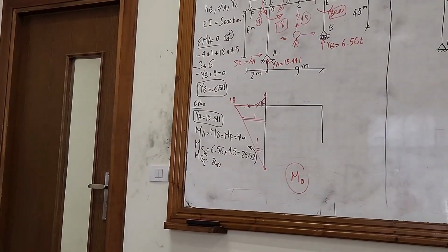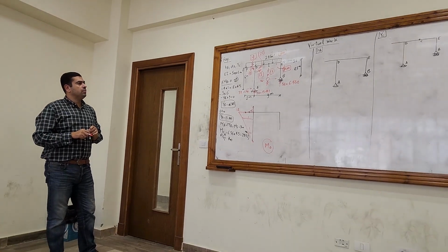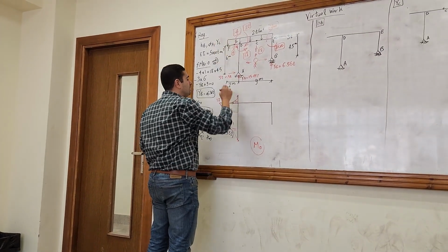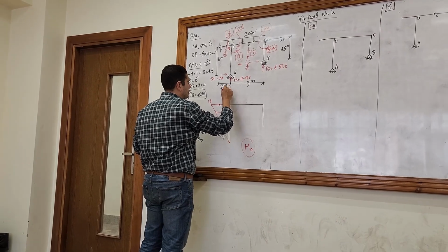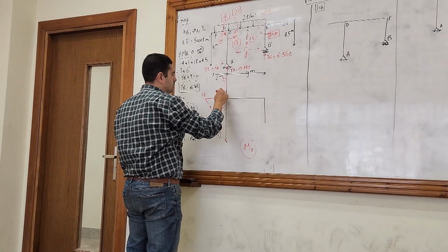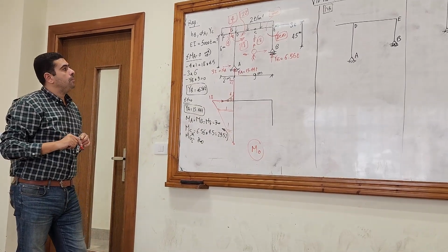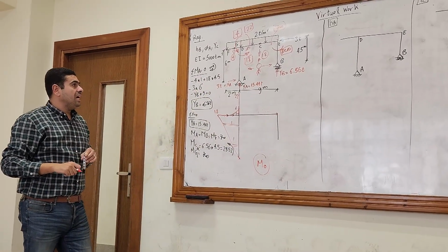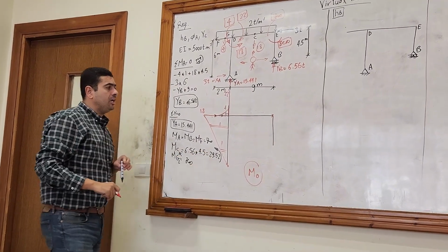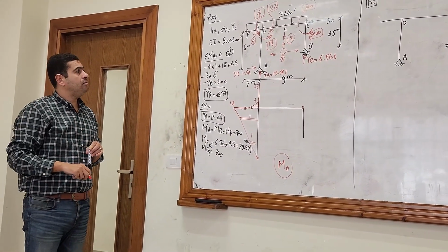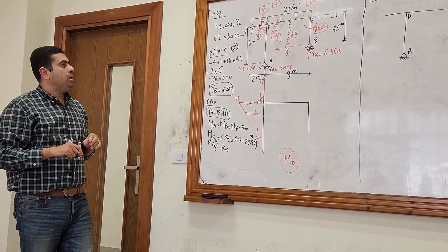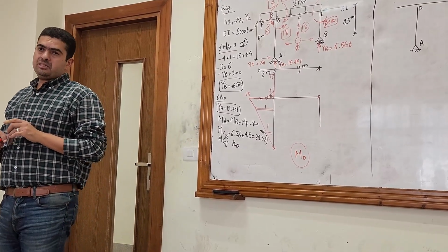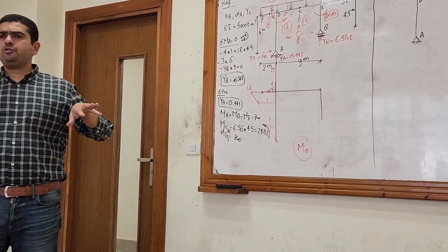Okay, let's go to the corresponding member DE, the horizontal member DE. The moment at D is 22 and the tail is upwards. And the moment at E is 0. And the moment at C was 29 and a half. Are you sure, 29 and a half, downwards? Let's make a D. We are now in Structure 2, not Structure 1.